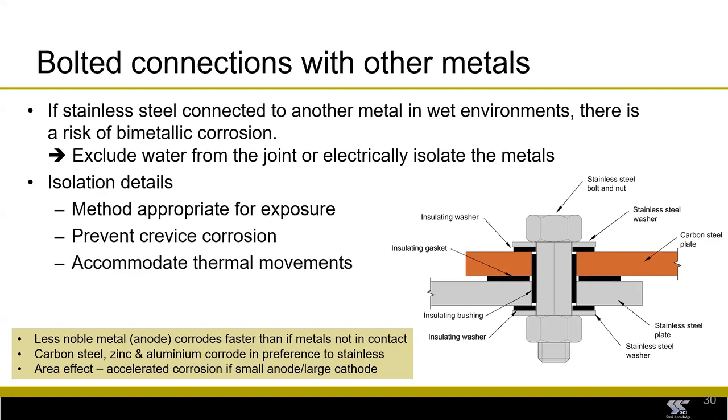But that's not a done deal. It depends on how corrosive the electrolyte is, and it depends on the area effect. If you have a carbon steel fastener in a stainless steel plate, that's bad news, and you really don't want to do that, because the carbon steel bolt will corrode quickly, providing there's a conducting electrolyte present.